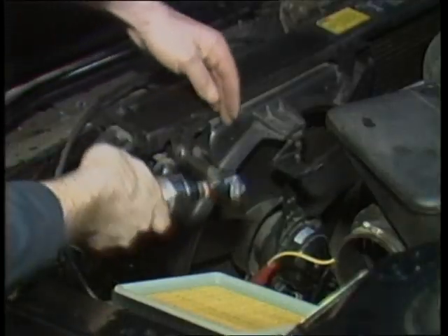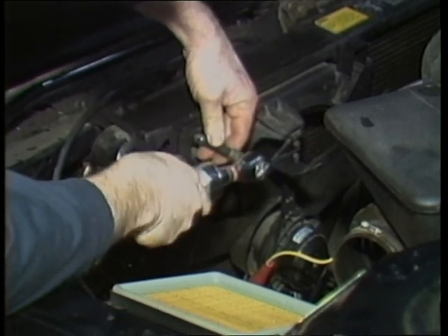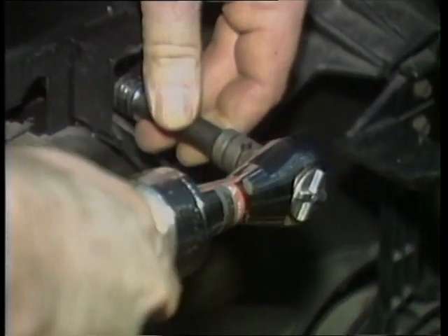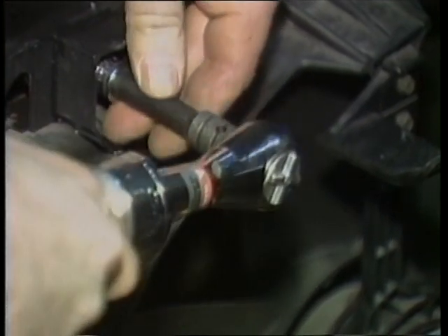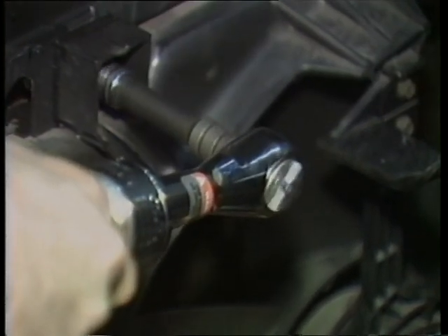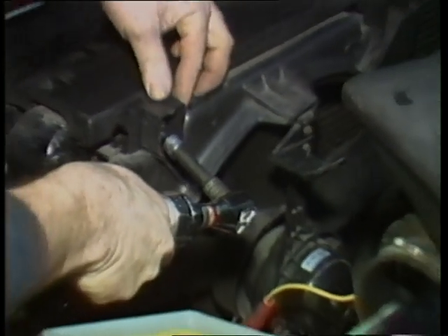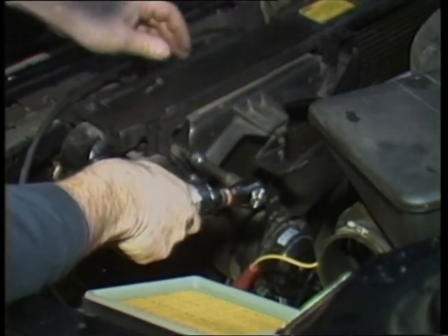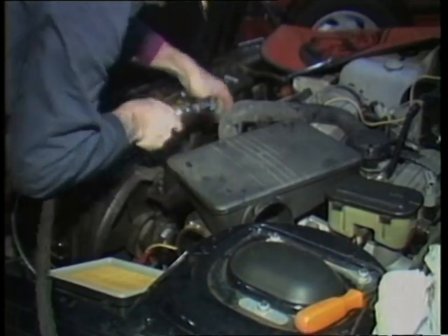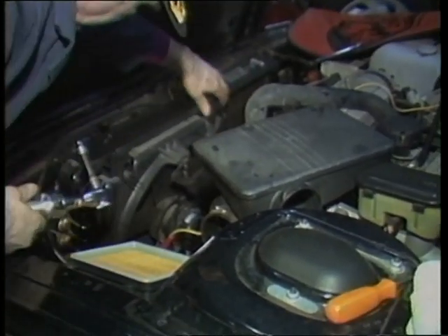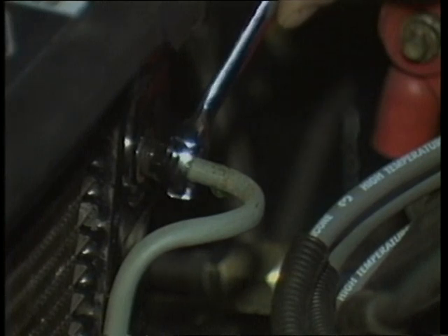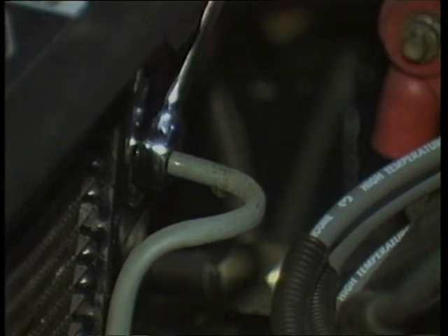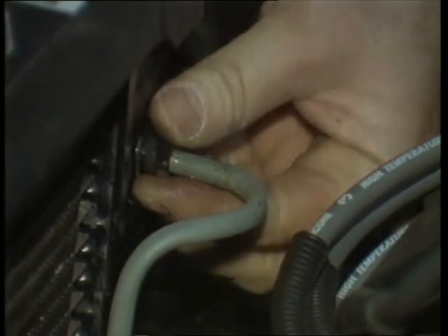If the shroud is cracked or broken, repair or replace it. Without a fan shroud, the engine can overheat because air will bypass around the radiator. Pull the shroud or electric fan back and away from the radiator. If needed, use a tubing wrench to unscrew and remove any oil cooler lines. This will let you lift the radiator out for service or to send it to a radiator shop.